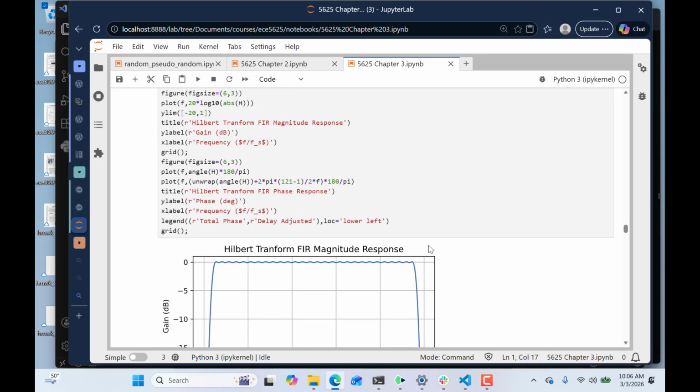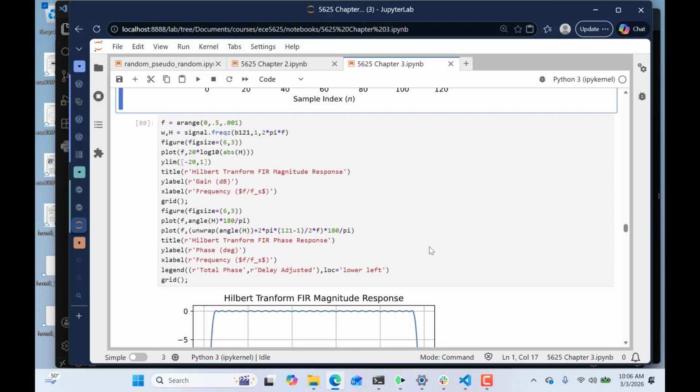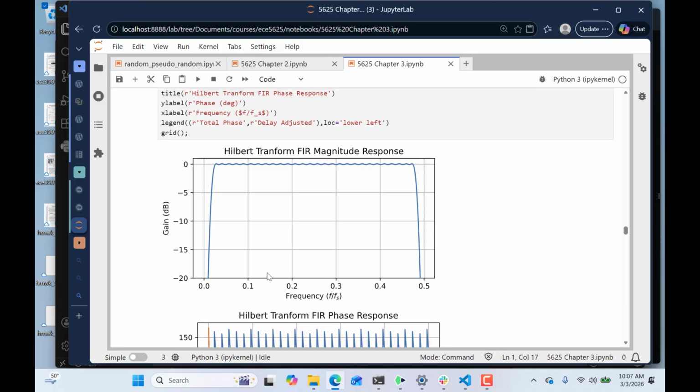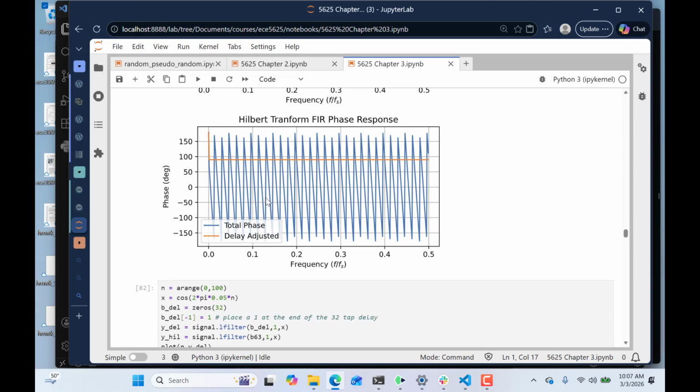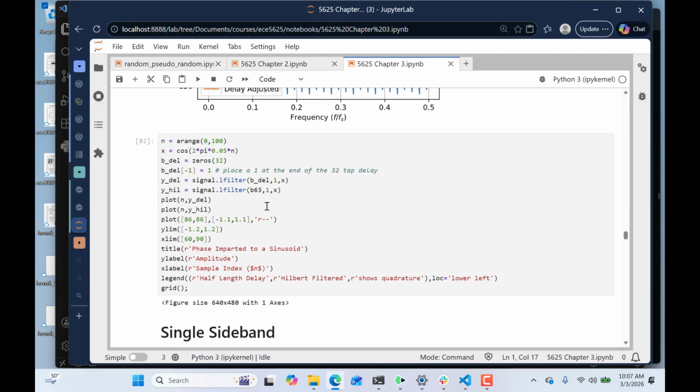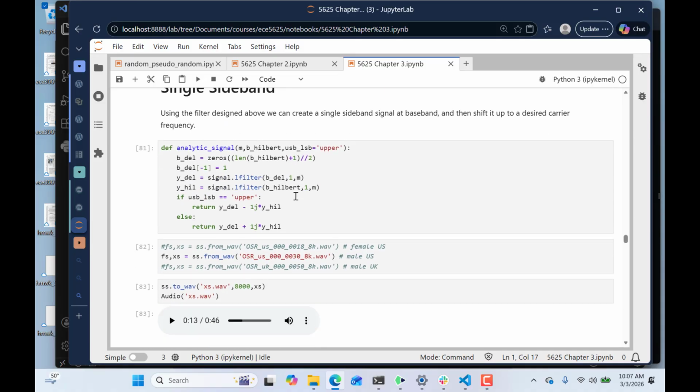There's the impulse response, and if I look at the frequency response for one of these filters, we see that from 0 up to the folding frequency, it looks very, very flat, but notice, like I was showing you before, there's impairment down here. It's not passing DC, and it's actually carving away some of the response. So I'll probably have you look at that in a problem. It has a nice linear phase associated with it, and it has a steady 90 degrees on top of that. So it's got a linear phase plus a steady 90 degrees.